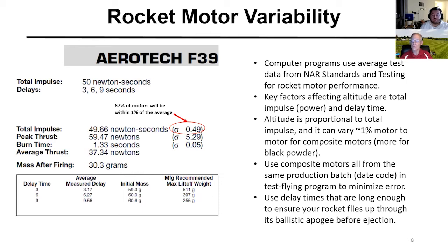You also need to make sure that you use delay times that are long enough so that your rocket flies up through its ballistic natural apogee before ejection. I have a slide that will show you why that matters.